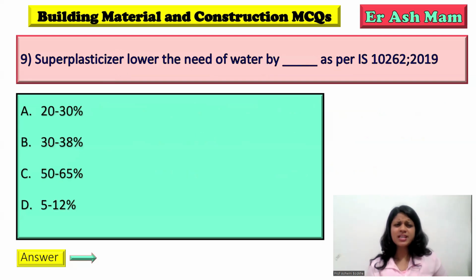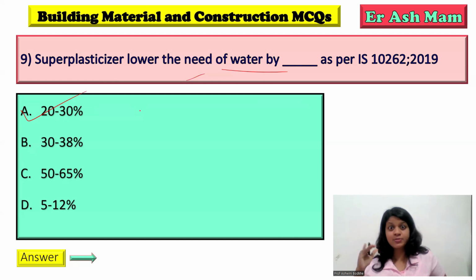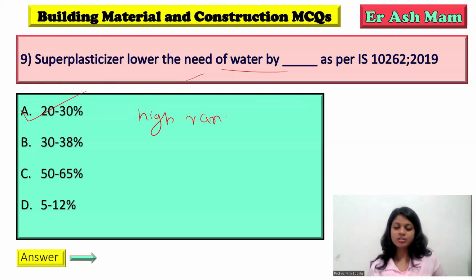C. Next is super plasticizer. It lowers the need of water by 20 to 30%. If you use a super plasticizer, it will reduce the need of water by 20 to 30%, not reduce the water itself. It is also known as a high range water reducer.